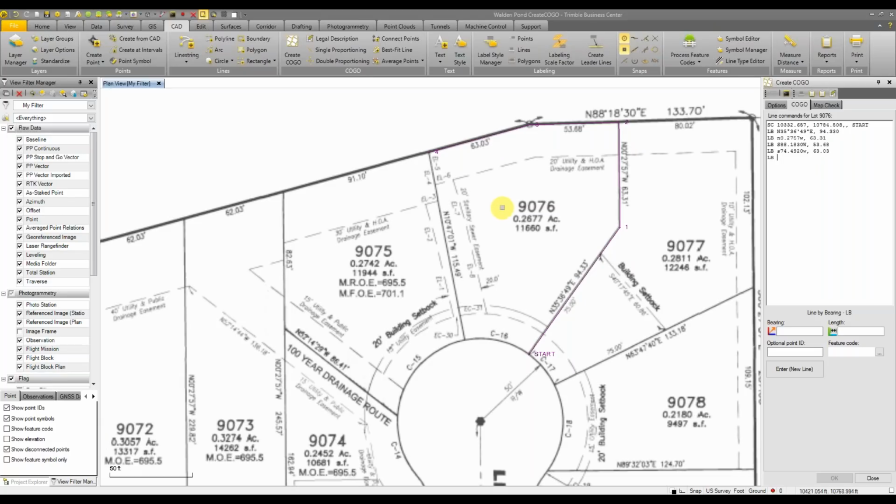It follows the azimuth. So from 0 to 90 on your azimuth, it's quadrant 1, then 2, then 3, then 4. So this one would be quadrant 2. 2 space, and this is 10.4701, comma, and 115.49 for your distance.